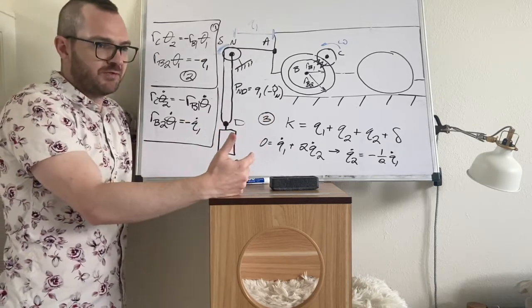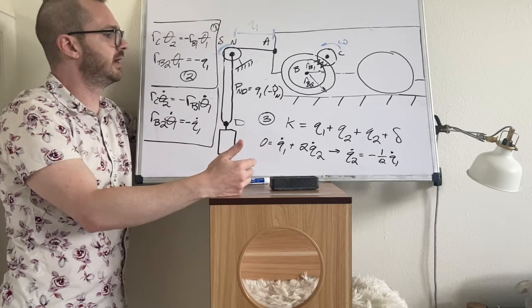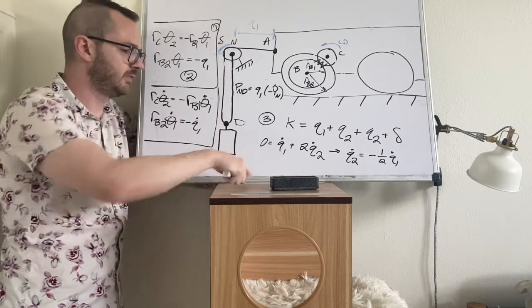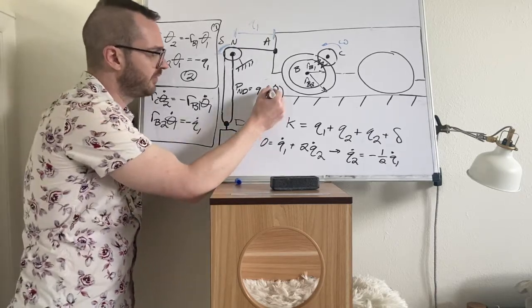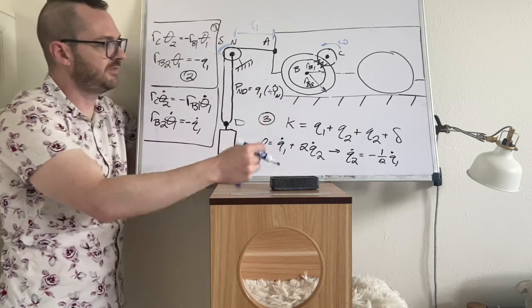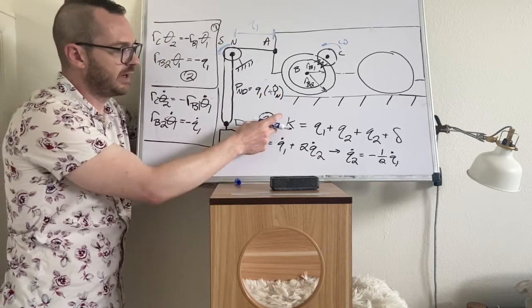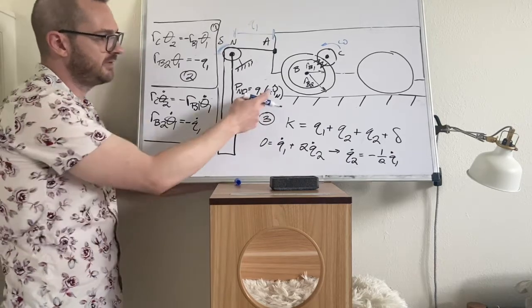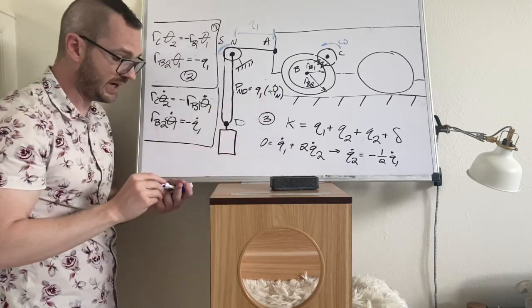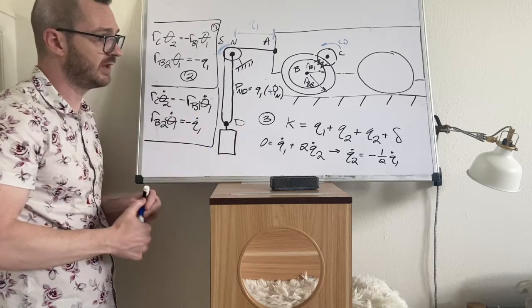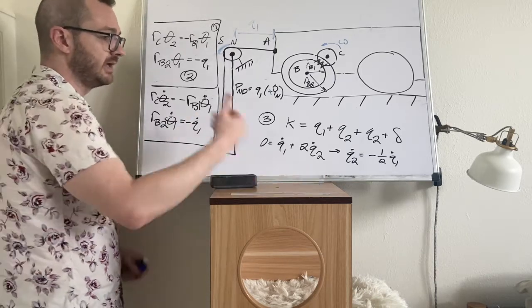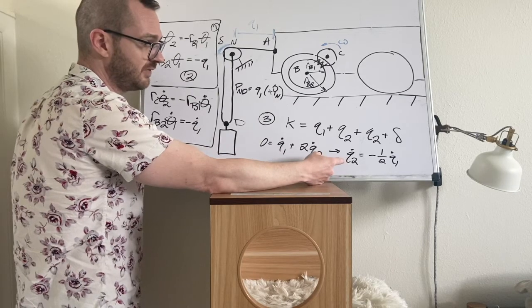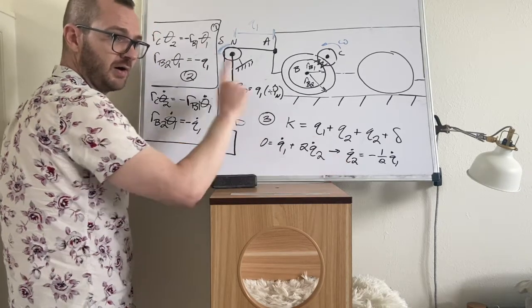So maybe in some problems there's no best or perfect way to do it. This is why when I work these, I have just trained myself to always do these things as positive. And then if I have to sort something out in a constraint equation somewhere else, hey, that's okay. I like to always define these things positive because when I get to the velocity level, it makes sense that if Q2 dot is positive, that means it's going up.